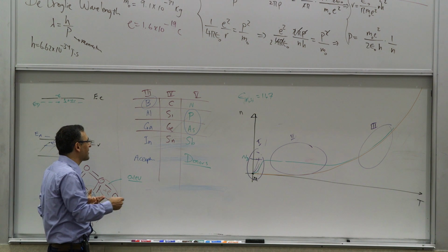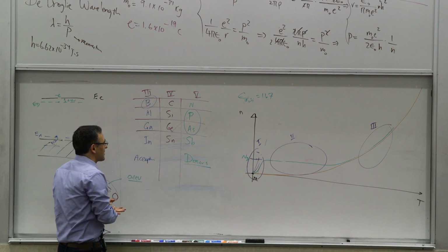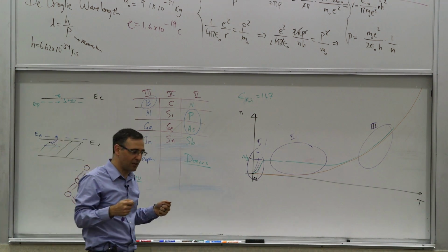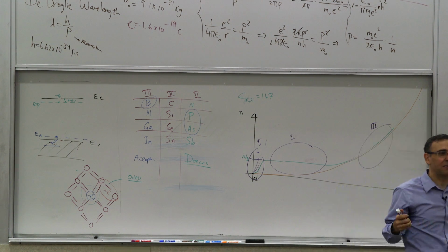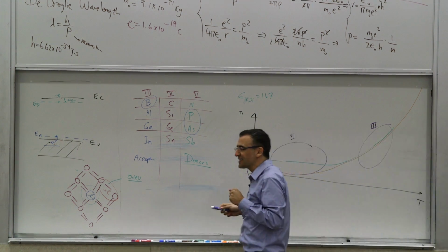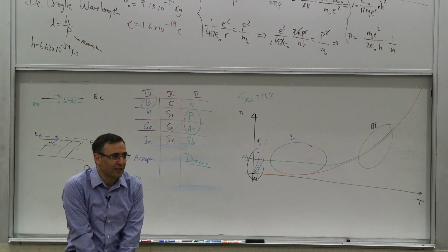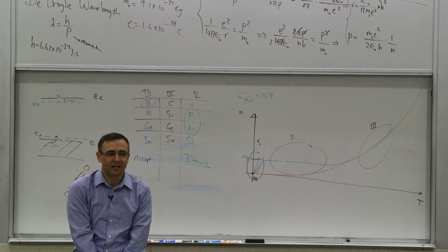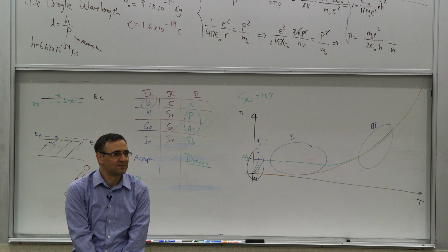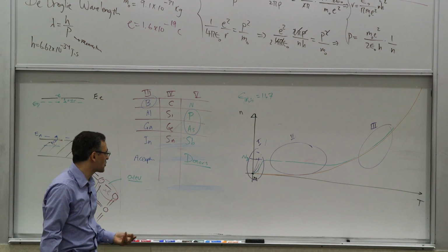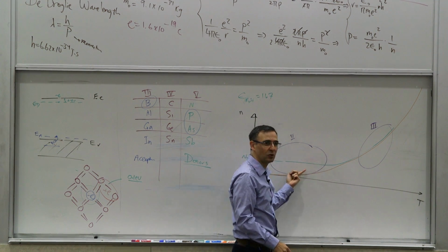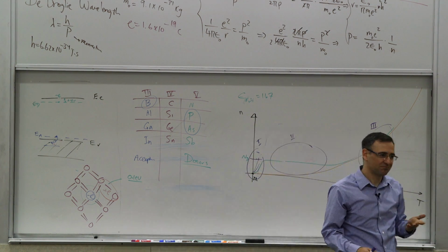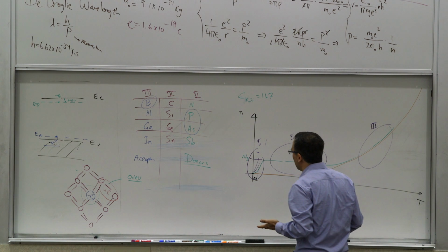Now, there's another thing. We talked about semiconductors. So silicon is one of the typical ones. In the past, germanium by itself was used. When I was a kid, half of the transistors I used were germanium transistors. And germanium has a smaller band gap than silicon. So let me ask you this question. What's the problem with a germanium transistor if it has a smaller band gap than silicon? What would be the problem with that? Yeah, less temperature stable. That's correct. So what happens is that this thing happens earlier at a lower temperature, right? This orange curve will come in. So as soon as it heats up, it starts getting pretty bad, right? So you have to be careful about that.